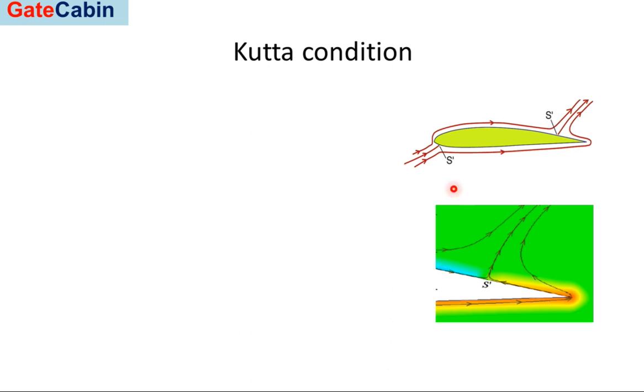So as we can see here, whenever air moves over an aerofoil kept inclined to the flow, over the aerofoil surface there are two points where the flow gets stopped, or reaches zero velocity, which are stagnation points. One point is near the leading edge on the lower surface, and another point is near the trailing edge of the aerofoil on the upper surface.